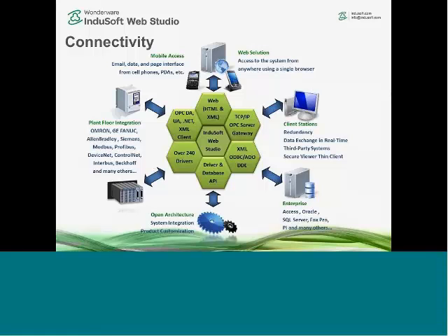So being able to communicate to these things like temperature controllers and get that information out of those devices into InduSoft Web Studio tags and then out to a database is quite amazing. Maybe not even communicating to the PLC, communicating directly to those temperature controllers or drives or motion controllers. And never before did you think that you could get information up to a database from those serial legacy type devices. So it's kind of neat.